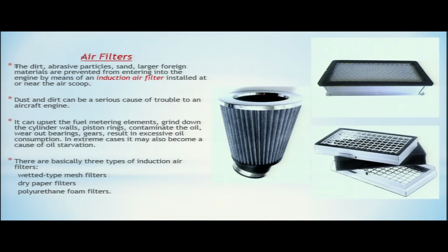That means the lubricating system may get clogged, the orifices inside the system can clog, the oil gets contaminated, there may be leakages, and finally there may be oil starvation.